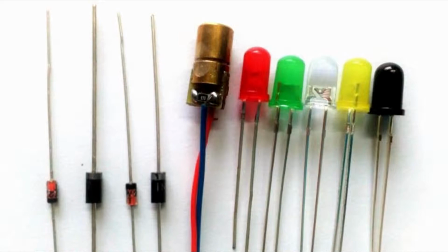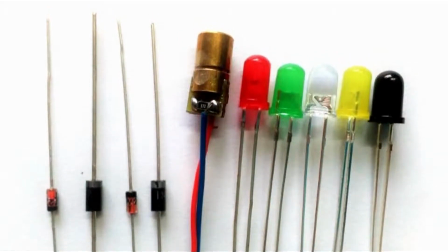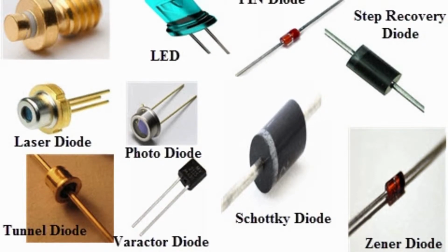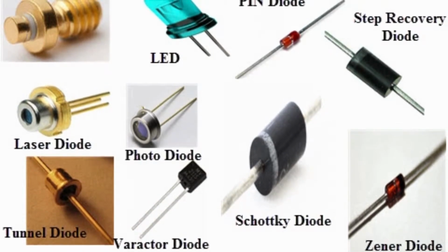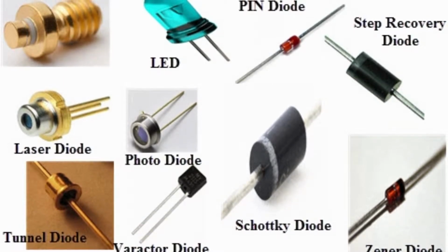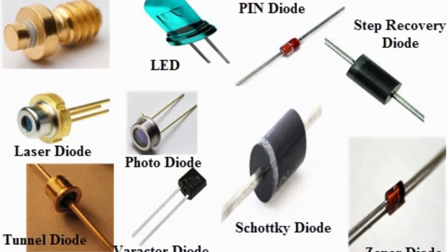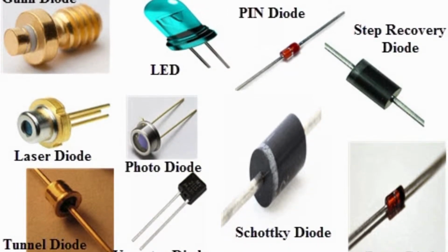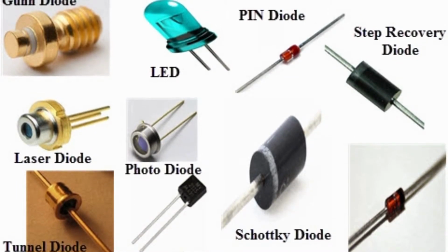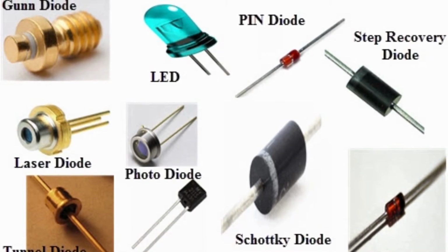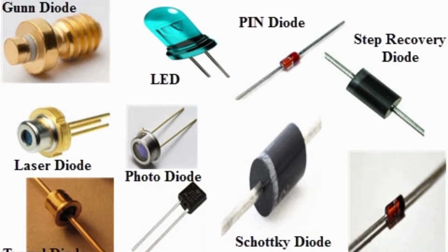As already mentioned above, the diode resembles a one-way switch, so it can either be in a state of conduction or in a state of non-conduction. The on state of a diode is achieved by forward biasing, which means that positive or higher potential is applied to the anode and negative or lower potential is applied at the cathode of the diode. In other words, the on state of the diode has the applied current in the same direction as the arrowhead.